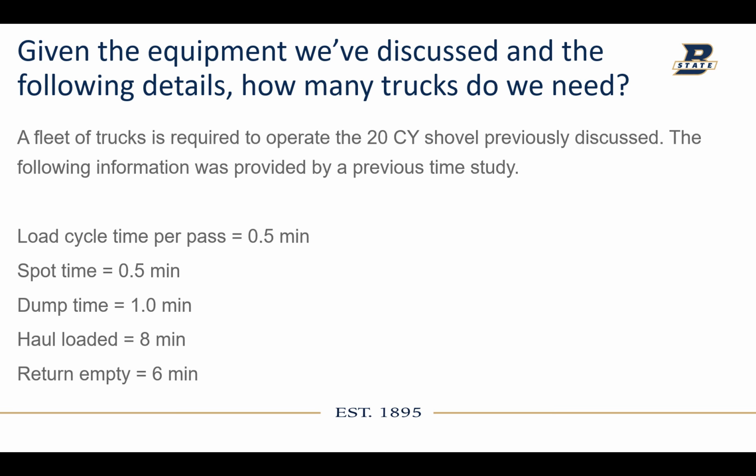So for this, we are going to assume that the availability is 100%, and that there's no delays involved. You can involve whatever delays you would like. Generally speaking, there will be a dozer, especially if you have a large electric rope shovel, that will clean up around the shovel, and that's because it can dig big material, but it doesn't do a very good job of cleaning around it. So they use some sort of dozer for that. In the cases that I'm familiar with, we used a wheeled dozer, and it worked great. But we're going to assume that those are 0 for now.